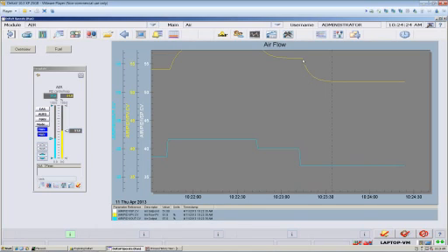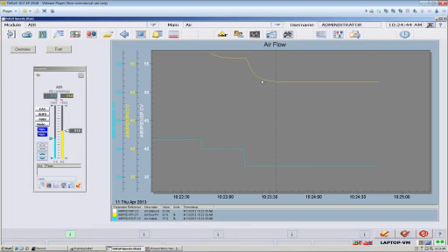So I went from 23 and 14 seconds to 23 and 35 seconds. 21 seconds. 21 divided by 4 is about 5 seconds. My time constant is 5 seconds. So now I know my dead time is 2 seconds. My time constant is 5. And my final piece of information I need to know is gain.